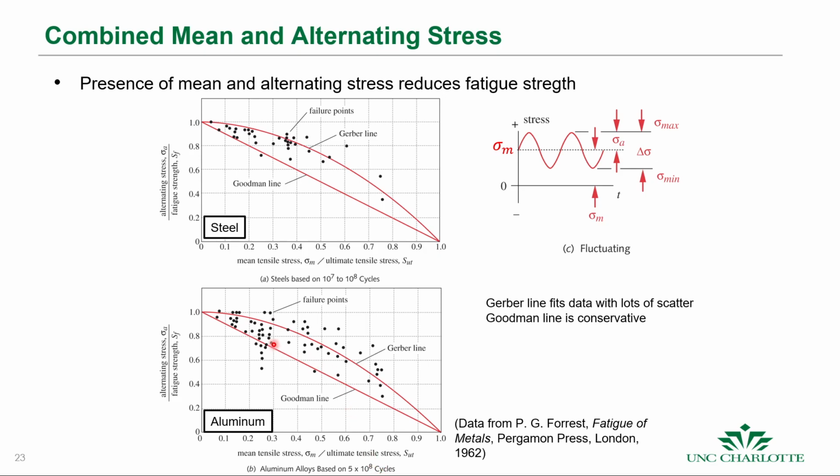The way that we use this is we calculate the fatigue strength for that material and correct for it, then calculate our alternating stresses and divide by those. We calculate the mean stresses present due to those cyclical loads and divide by the ultimate tensile strength, and we get an XY point on this chart with the normalized alternating stress and normalized mean stress.